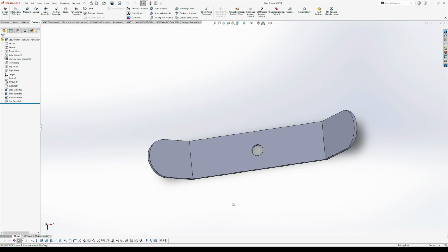However, there are a couple cases where it is necessary to do so, especially when the model you create will be used to manufacture the design in the real world. Whenever you are going to create a model using a machine, such as a 3D printer, you need to make sure you build the limitations of your chosen manufacturing mode into the model when you develop it. For example, it is much harder for a 3D printer to make sections of a part that are only supported by the sides and not the hot plate that the model rests on.